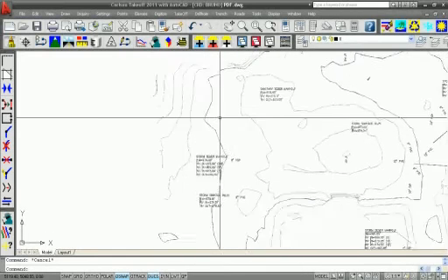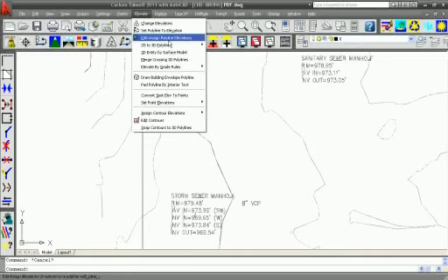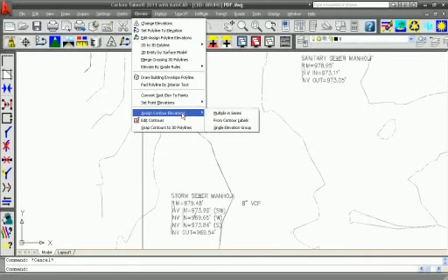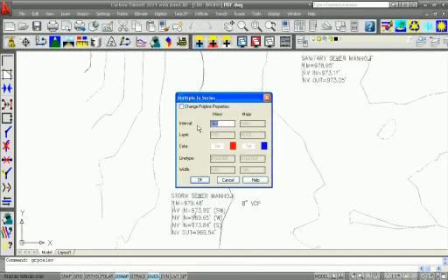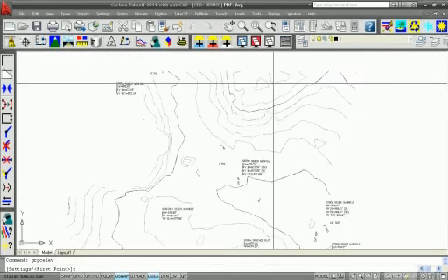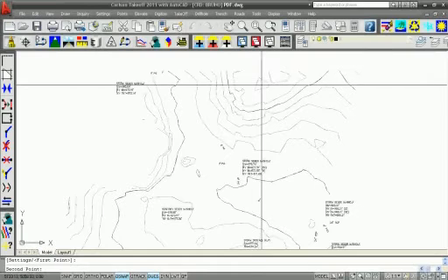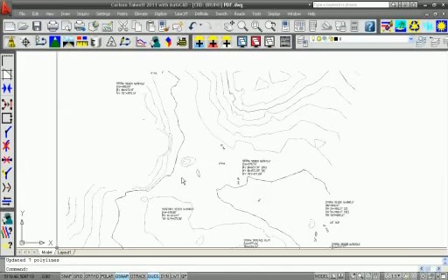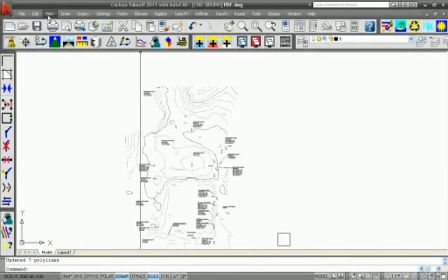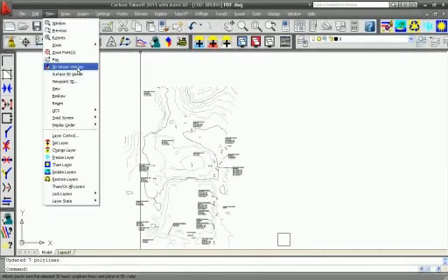Okay. And then we have different elevate commands that says elevate, assign contour lines, multiple in series. Say that these were 2-foot contours, and I'm just going to make up some numbers here, going through here to here. Say the first contour was at 100, going up in elevation. Okay, updated 7 polylines, and if I look at my 3D viewer window,